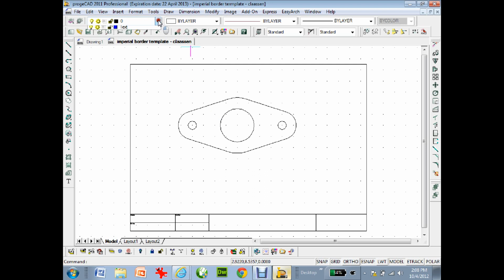Okay, so next is center lines. So I switch over to my center lines. And again, if I got my center lines set up, and I'm going to take off ortho, I'm going to make sure my snap's on. Okay? And I'm just going to grab here, go across. If I got it set up right, I could actually set this to get to the right spots. I'm done already. Right? Do my center line this way.